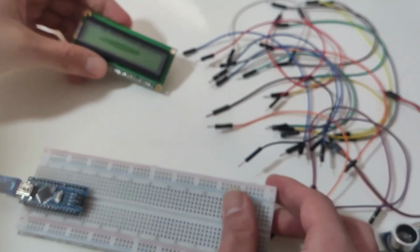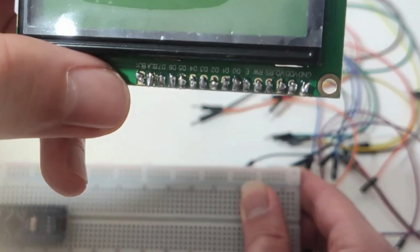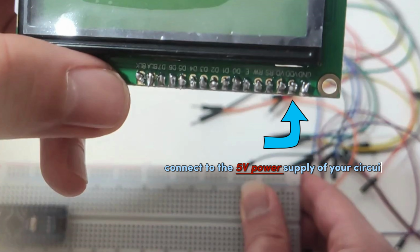Like always, let's start by assembling our circuit. As you can see, this display has 16 pins, and I'll explain each one briefly and fast. The GND pin should be connected to the ground, GND, of your circuit. The VDD pin is your power supply. This pin should be connected to the 5V power supply of your circuit.